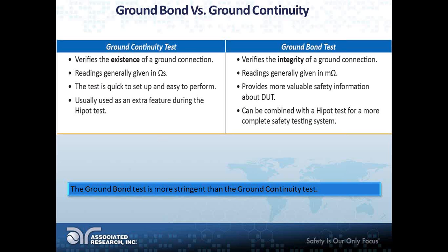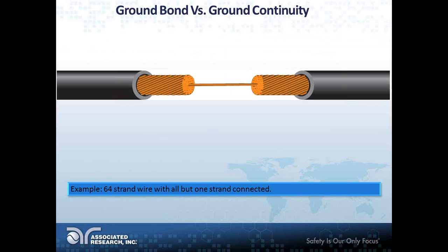Maybe you don't have to go the full-blown 20, like say your type testing says 25 amps. Okay, great. And then for the routine testing in your standard, as we saw with 61010, it says no current is specified, just show that the path is there. Maybe you do a 5 or 10 amp test. You're still loading it down. You're still verifying the integrity. You're just not going full-bore type testing. That's also acceptable. Obviously, you want to check with your safety agencies, but I can tell you for that particular standard, even though the routine aspect tells you to do 25 amps or 40 amps or 2 times rated current, the production aspect says no current specified, so you can get away with something else.